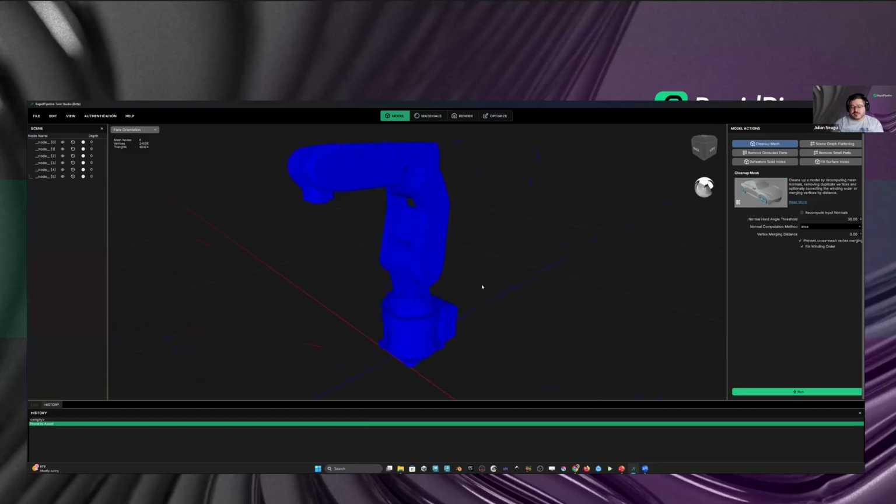But right now, the action is pretty straightforward and flips per mesh lump. It calculates for all the triangles of the scene which direction they should go. Then as an after step, it checks, for the whole mesh lump, what's the ratio between triangles which are supposed to show one way versus the other way. And then it harmonizes the triangle order per mesh lump. So at the end, it doesn't matter whether it's a single triangle or a whole part which has incorrect winding order. It will deal with any of these issues generally.